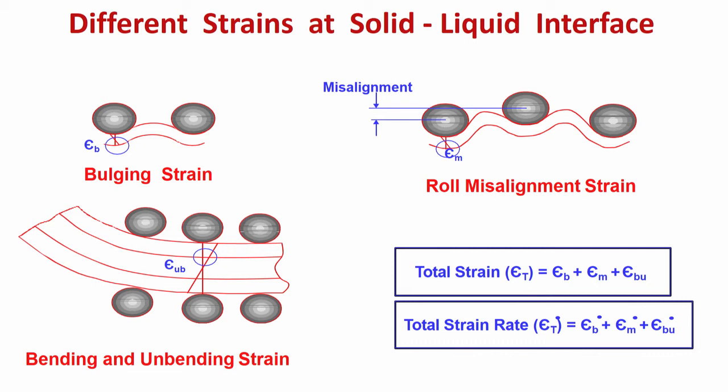If it is a slow change in profile, the strain rate will be slow. If it is a sudden change in the profile, that means between one particular roll and the next there is a lot of angle, we call it a sudden change. If it is quite large, then the strain rate also is more. So, the strain is important, strain rate is also important. Strain rate also should not be very high.